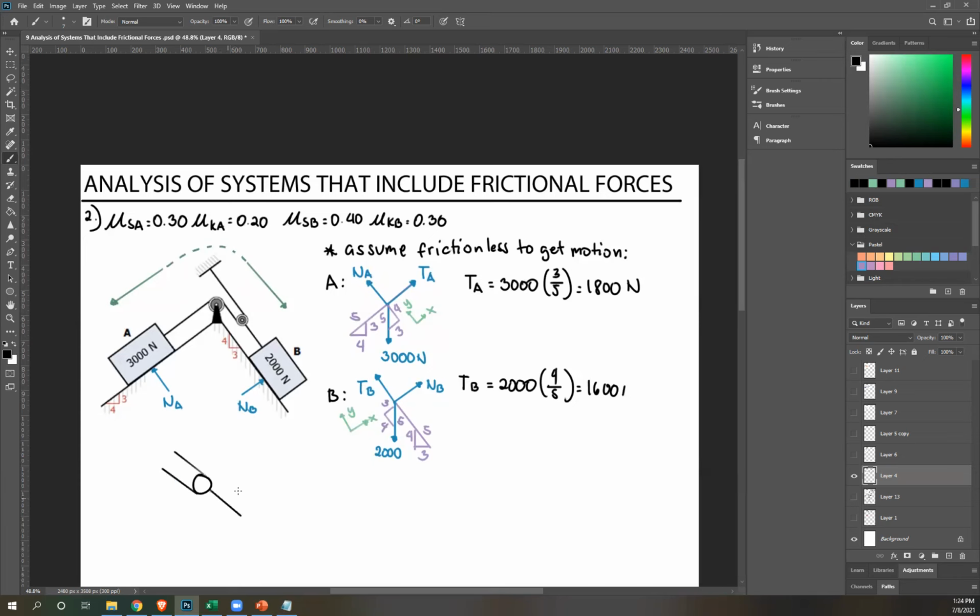So you have this pulley. Obviously, this is your tension TB, right? It's this wire. Now, how about these two? So this is TA passing through here, meaning this is also TA. Remember, frictionless pulleys just carry the same tension. Now same thing, it passes through this pulley and goes out here, so that means this is also TA.